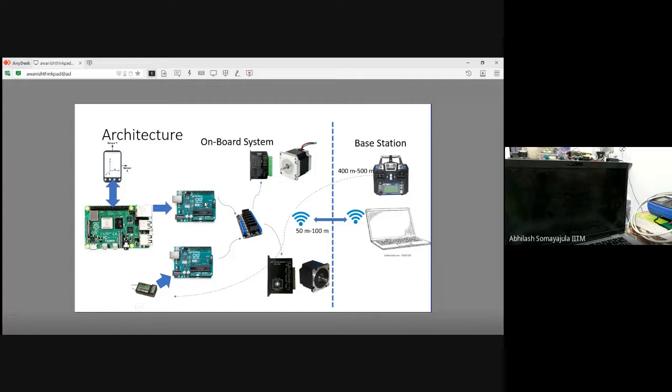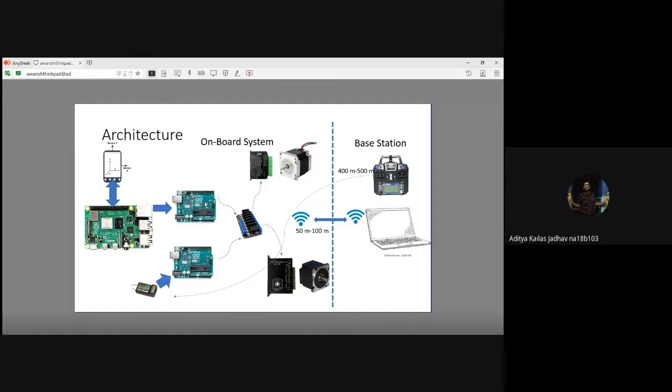Also, you don't want signals from the Raspberry Pi messing up your control if they may interact. You want to avoid that possibility altogether by keeping the two systems separate. It's a kill switch, right? Whenever you go into a kill switch module, you want to keep redundancy there. That's the primary idea, how I look at it. It's not that you can't use one, but then the Arduino becomes your bottleneck. Is that making sense? Yes, sir.